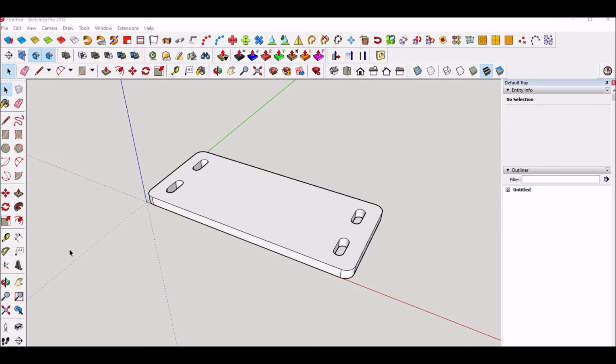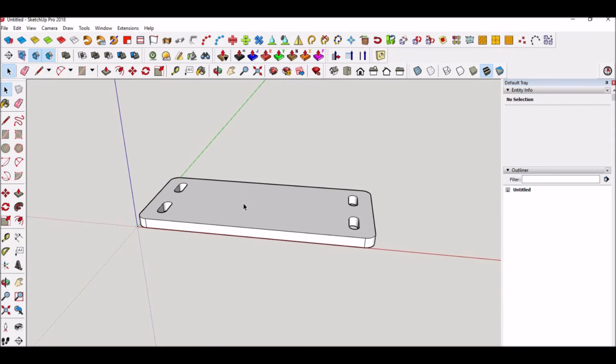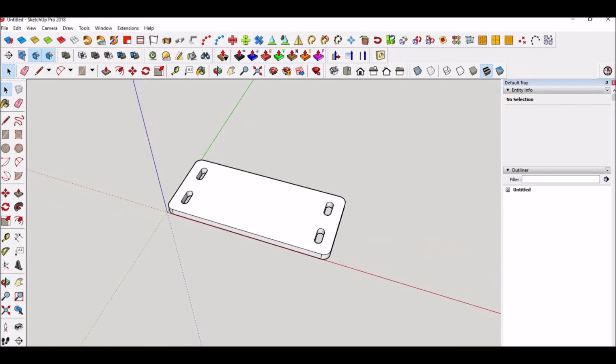Okay, so I went ahead and finished drawing the slots and then pulled this up. I don't know how you guys did it, but all I did was draw in a guide that was 1/2 inch in, half an inch down, drew this slot in, and then used the copy move tool to bring it down here, and highlighted these and did a copy move to mirror it over here, and then I did the extrusion very last. So that's how I did it. Anyway, alright, let's move to the next section.